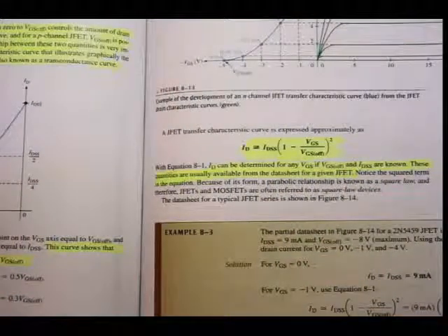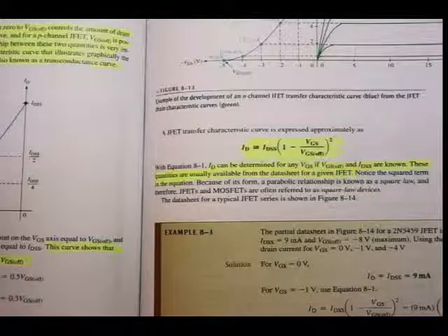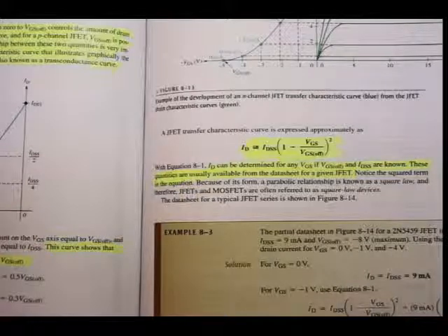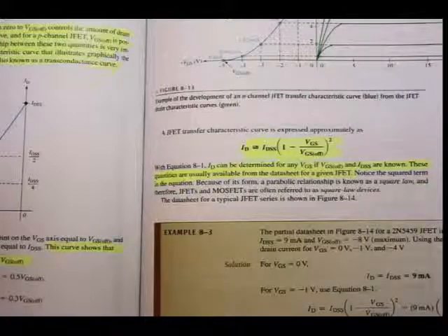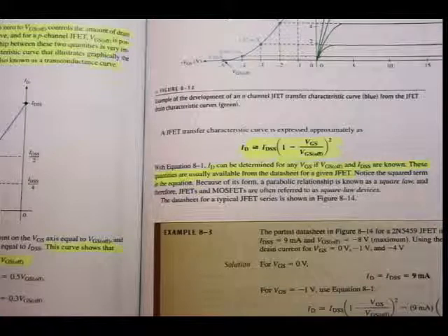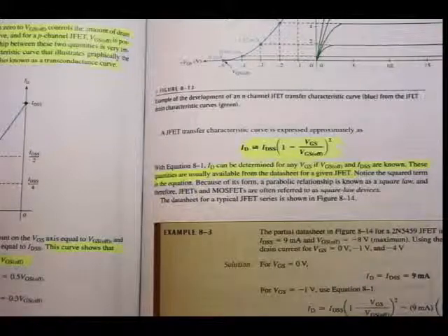If you go back to the textbook on page 377, equation 8.1, that is what I need to be able to calculate values of ID for different values of VGS. So what will I normally do? VGS voltages are normally fairly low, 4, 5, 6, 7, 8, 10 volts or whatever. So I would do, as they've done here, do it in steps of 1 volt. You can see it's -1, -2, -3, and so forth. Then I go and calculate the values of ID using this formula.